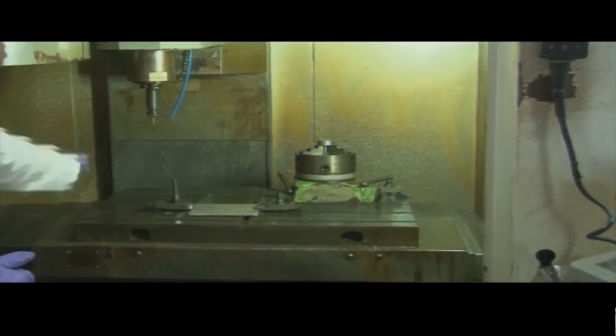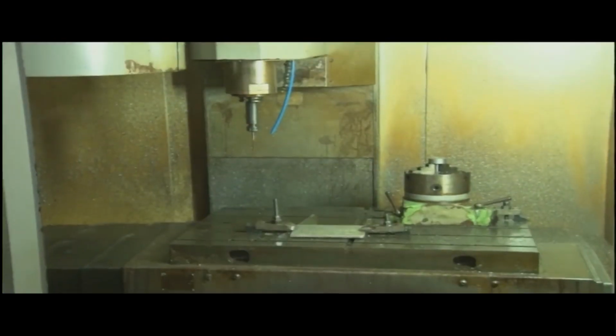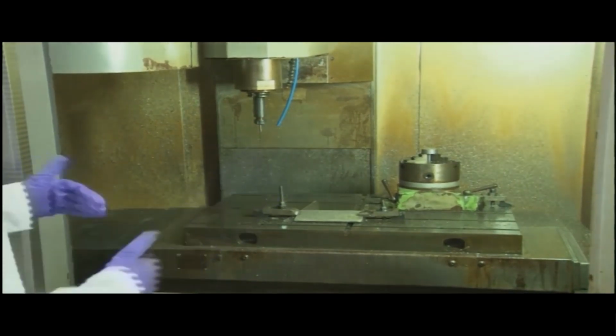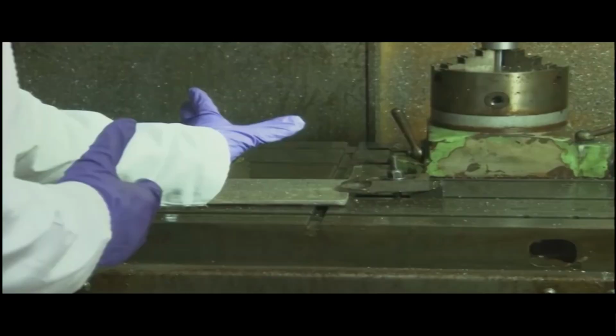This table is big. In X direction, 650 mm is the size of the job that can be held here, and in Y direction it is 500 mm, that is 0.5 meters. In Z direction, we can hold a 400 mm thick block. So, the dimensions become 650 by 500 by 400 millimeters cube.